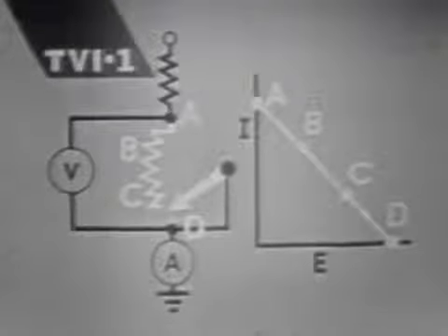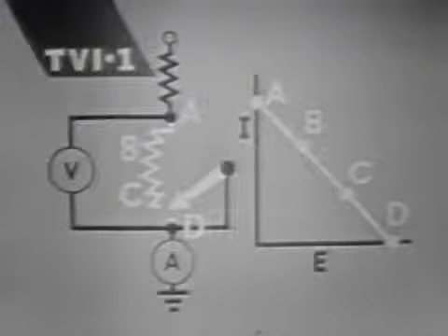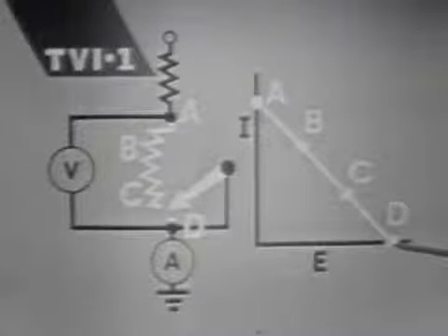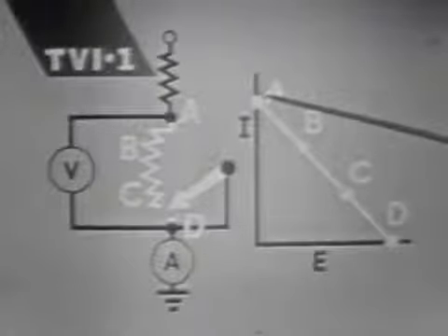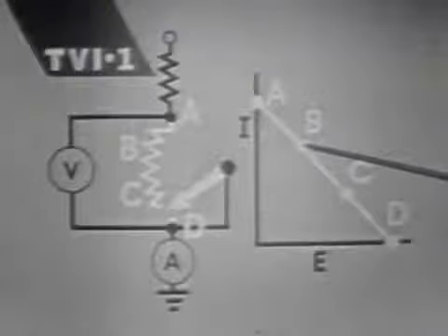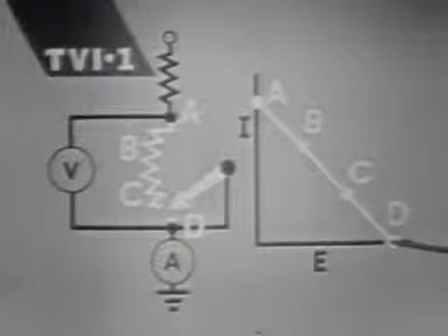Using a simple resistive circuit as an example, we can describe a basic load line. A load line is a line that represents all possible current and voltage values in a circuit. Point D is determined by the applied voltage, and point A is determined by the load resistor. The points in between A and D are controlled by the variable resistor.